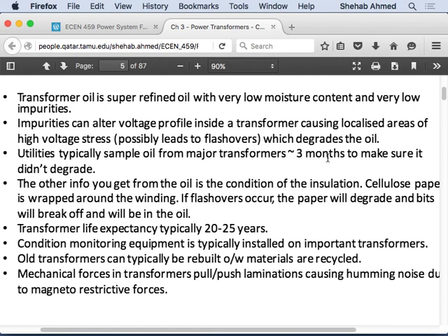So similarly, the insulation has a certain lifetime, which is what's going to limit the transformer lifetime. The metal itself doesn't go away, the copper doesn't go away, but what degrades is the insulation material, and of course it ruins the oil. So you would have to change the oil, you would have to flush it out. If you want to, you can reuse transformers.